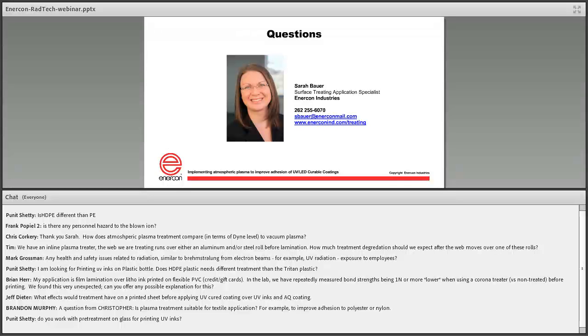Let's say you're getting your HDPE bottles from one supplier and now you're getting them from another. It's always good to requalify. You can do it very quickly with a dyne test or a quick little DOE to ensure that you're working with the right surface energies before and after, because we've seen that even a few dynes can give you a change in adhesion.